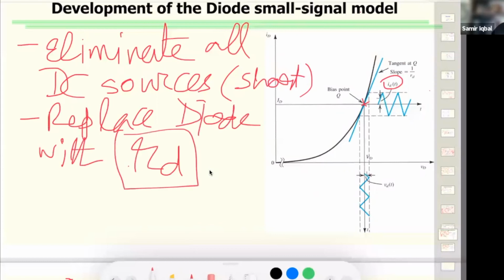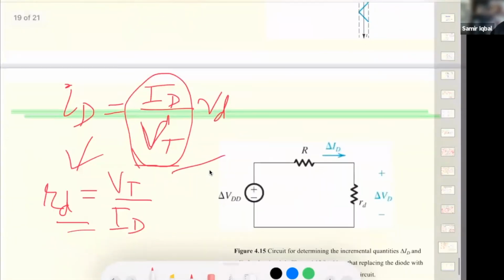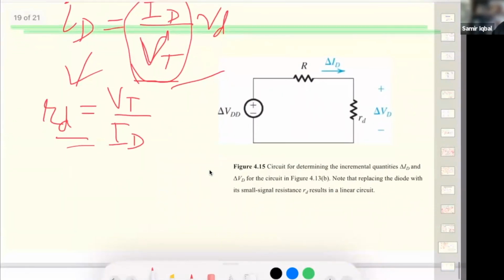When we do these two steps, our analysis becomes simple and straightforward. So we would replace this guy with this, and we just short. So if you look at this, we are not using VDD by itself. VDD itself is not there. It's been replaced by a short circuit.